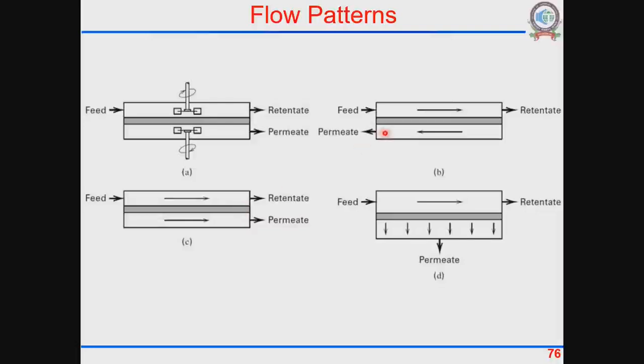In this particular case, we would write the flux, and therefore we would be able to calculate the membrane area required in a well mixed operation, in a plug flow operation, or in a counter current operation. Driving forces are going to change when we look at the concentration recovery in a counter current manner versus a co-current manner. Right now we will not go into those details, we will not calculate actually, but you can appreciate how the concentration differences will change, how the fluxes will change, and how in turn it will affect the membrane area required in all these four cases.